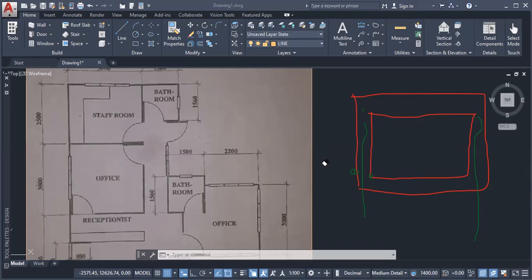In a case where we have center justification, take for example, if you want internal wall to wall measurements of 3,000, we would need to add half the wall thickness, well, full wall thickness, as from here.